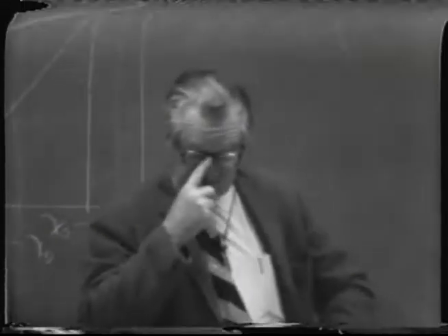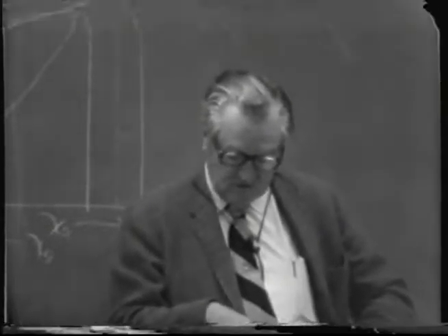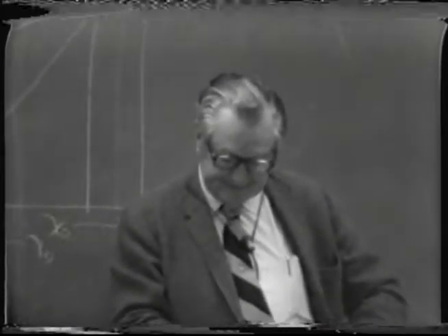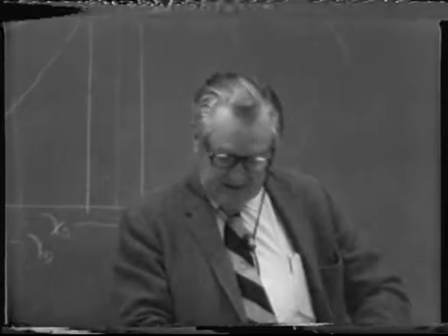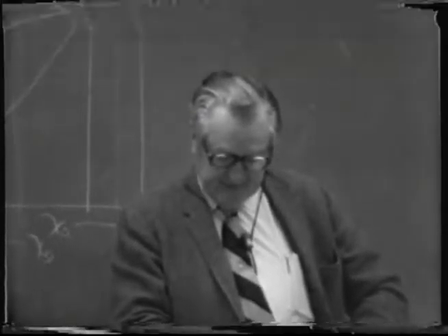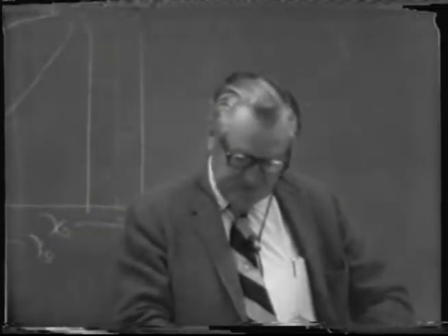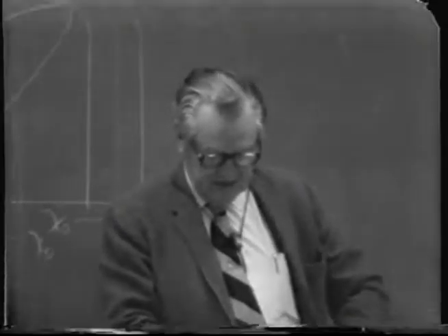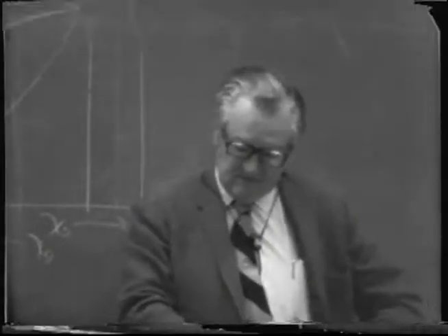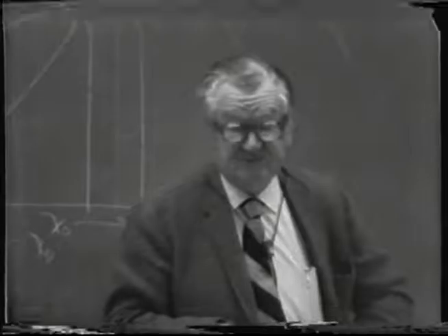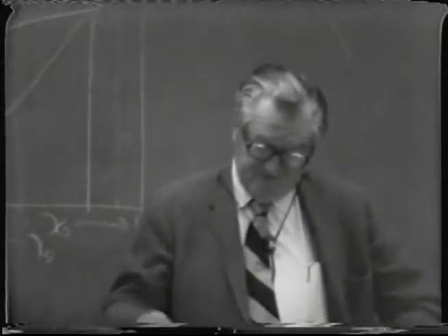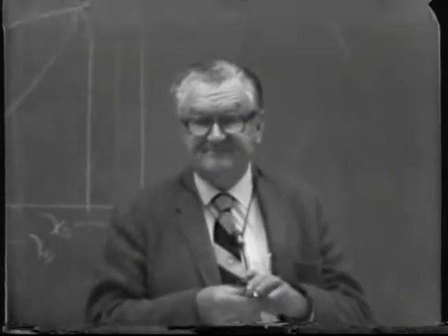Now you see, if you want to use these figures here for 10% ethyl alcohol as typical of the low alcohol separation requirements, that plate spacing of around 14 or maybe 15 to 18 inches would give you an allowable vapor velocity of somewhere between around 4 or 5 feet per second.